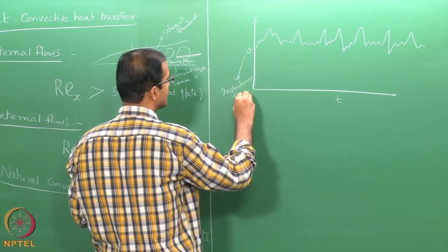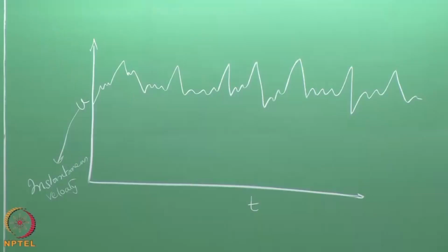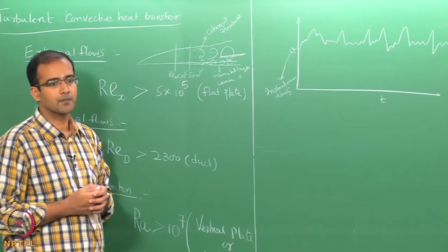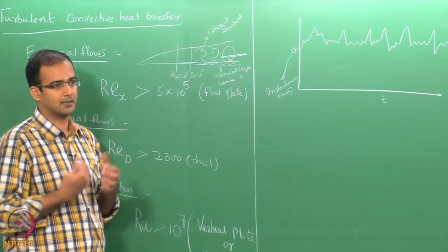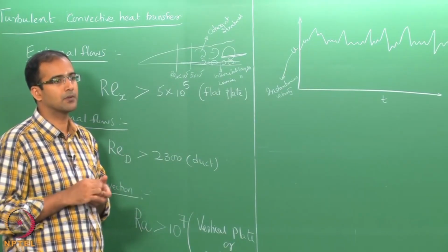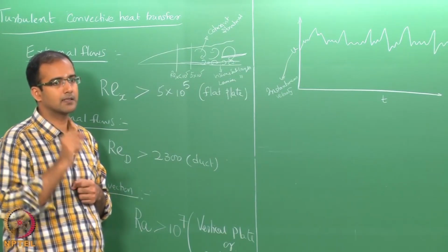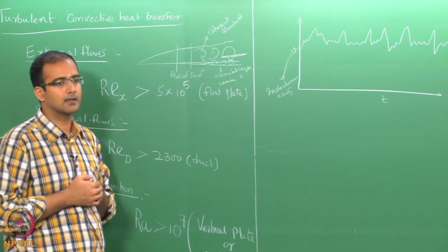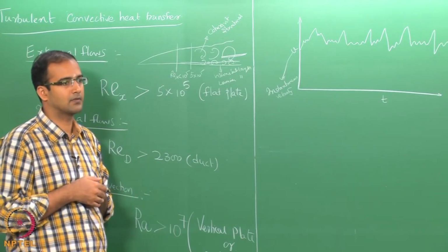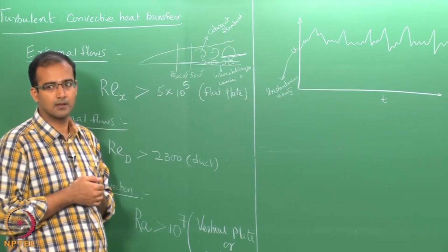That means this is at a particular point, and over time you keep monitoring continuously, okay, and you do not apply any filter to this. So, whatever comes out of the probe, and if the probe is quite sensitive, you have to pay attention that the probe is sensitive to all the time scales of turbulence, and therefore it should be able to resolve these fluctuations. Okay.